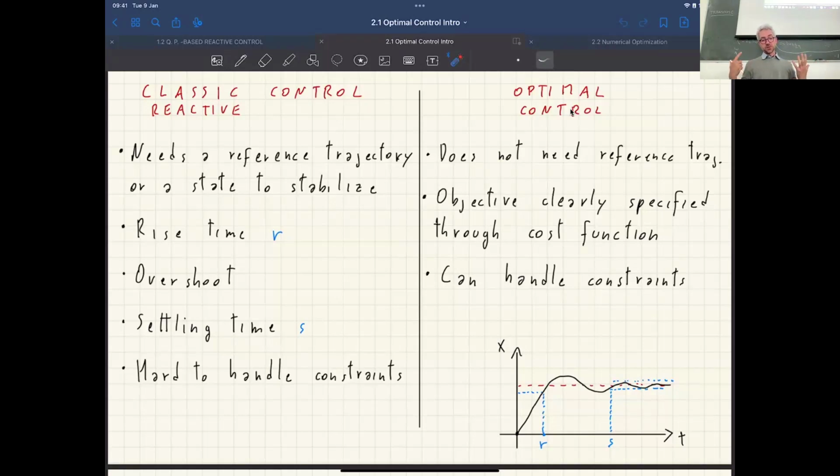If you want to handle position constraints, either at the joint level or at the Cartesian level, like when doing obstacle avoidance or self-collision avoidance, reasoning only about what's going on right now is not good enough. You need to look into the future, look at how your positions are going to change, because you need to start taking action now to avoid something bad happening in the future.